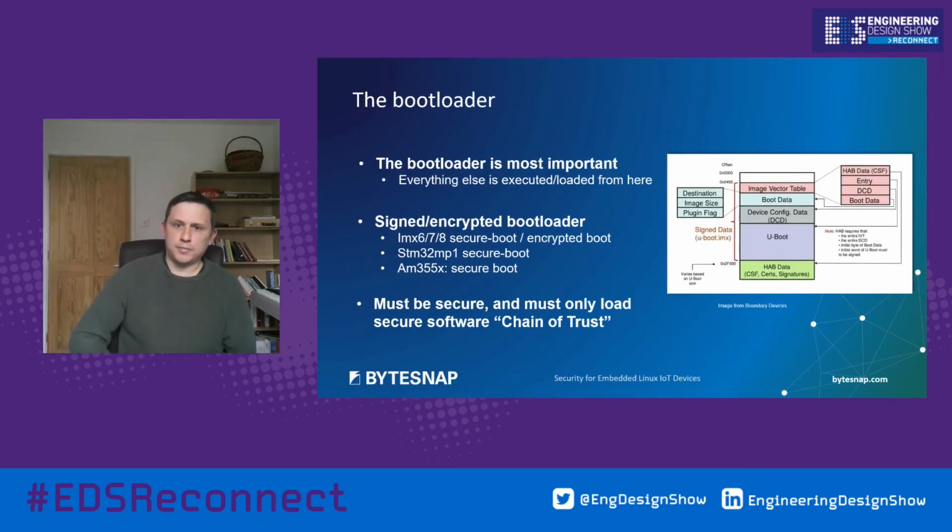Okay, so the bootloader. Bootloader is the first thing that runs on your device. If that's not secure, then nothing is at all. It doesn't necessarily need to be encrypted, but it does need to be signed. So what does signing mean? It means that the bootloader itself came from your company and your company alone.